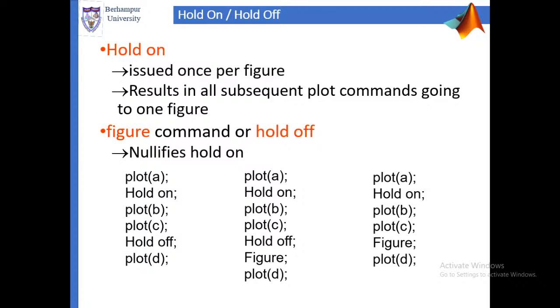The figure command or hold off eliminates the hold on. It automatically switches off the hold on command. So you will come out of the hold on command if you write figure after the hold on command, or if you write hold off after the hold on command. So this nullifies the hold on.